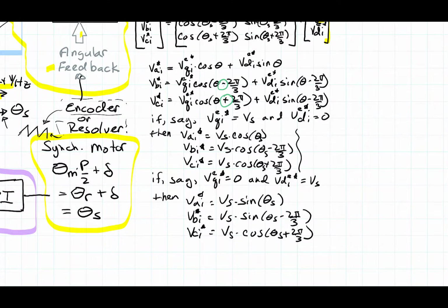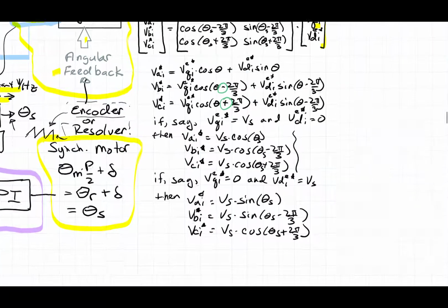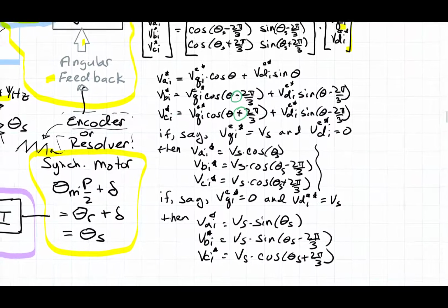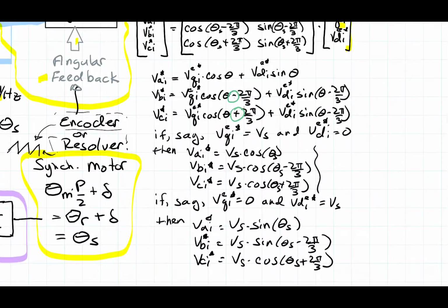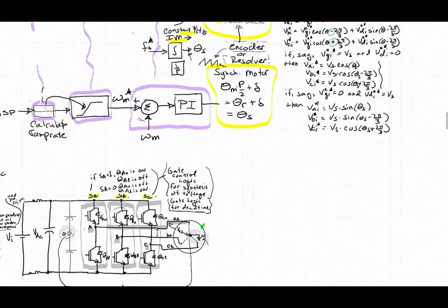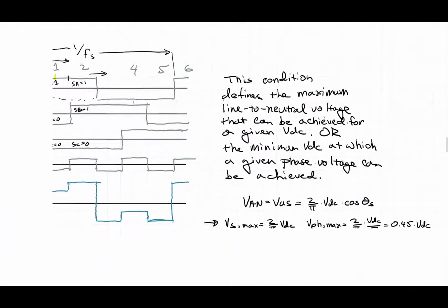And that's why when you swap any two leads on a three-phase motor, an induction motor for example, which is a really great example because the induction motor is just going to run in the one direction or the other, and if you swap the two leads, it'll go the other direction. And then this is showing you what's happening.